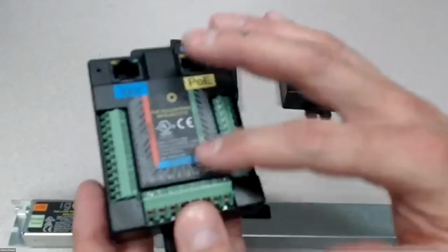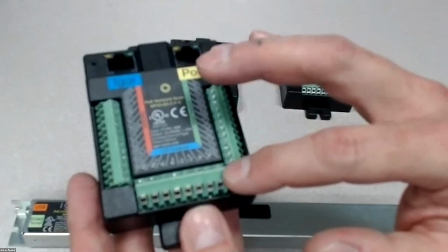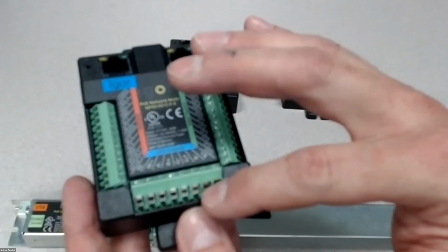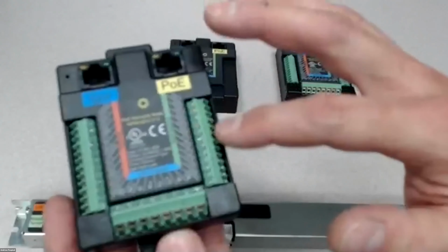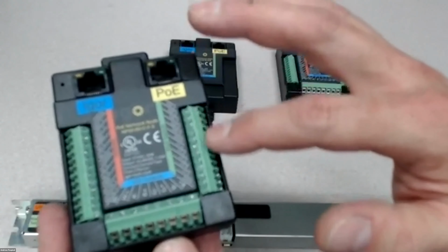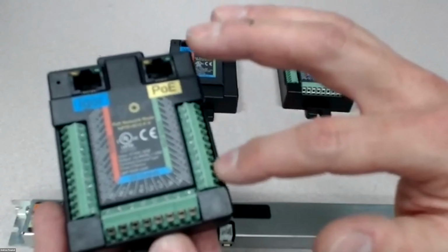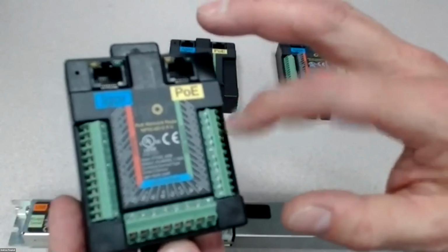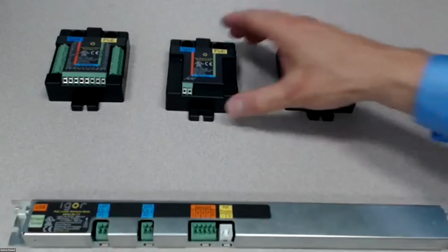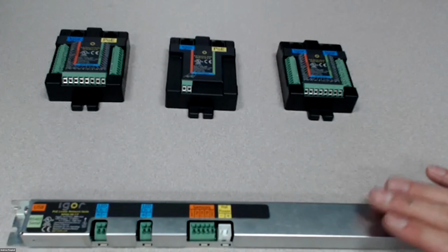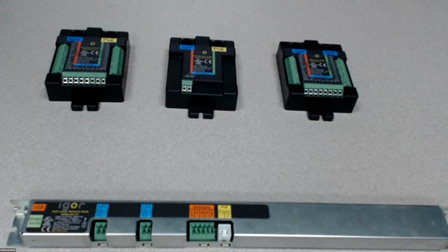Screw down terminal blocks on this model, accepting, depending on if it's the LED drivers, I think, up to 14 gauge wire, versus the sensor and the wall switch terminal blocks on the sides, which are for smaller gauge, 18 gauge to 22 gauge conductors. So a couple different examples that we're going to cover in more detail there, and then we'll get back to the Rev 6 node in that section of the presentation.